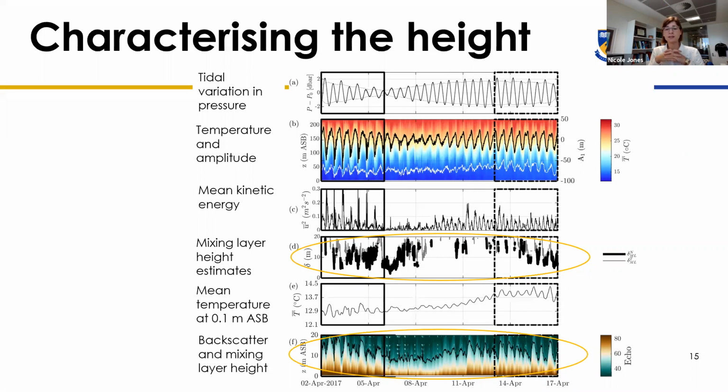And you can also see that there's quite a few gaps. The gaps occur for two reasons. One is because of the knockdown of that 20-metre thermistor chain. When we don't know the positions of the thermistors in the water column, then we can no longer calculate height. And then also you have some periods where it seems to go beyond the range of where we have measurements, because that was limited to 20 metres.